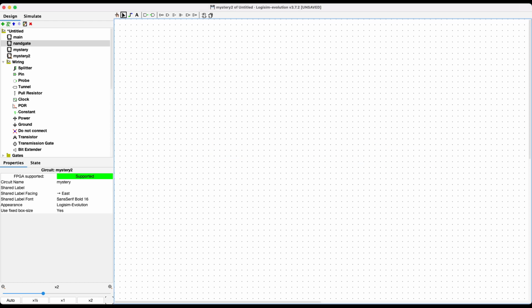Okay, so good? Okay, so if we start to put these things together in interesting ways, okay, now let me write this on the board, but let's say that I wanted to do addition. Okay, I want to design a circuit that's going to handle addition for me. Well, in order to demonstrate that, let me actually use the other board there. Let's just think about, how do I add a single bit to a single bit, right? Now, there are 4 possible combinations of what the 2 bits I'm adding are, right? They could both be 0, they could both be 1, or they could be 1 and the other, right? Okay, so let's write all 4 possibilities down.